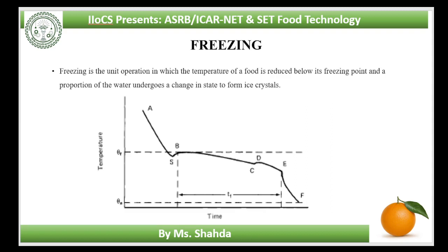During freezing, sensible heat is first removed to lower the temperature of a food to the freezing point. In fresh foods, heat produced by respiration is also removed. This is termed the heat load and is important in determining the correct size of the freezing equipment for a particular production rate. Energy of freezing is supplied as electrical energy, which is used to compress gases, that is refrigerants, in mechanical freezing equipment, or to compress and cool cryogens.